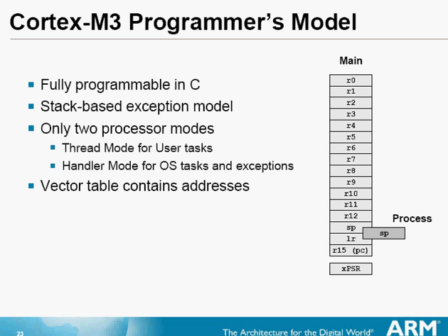Stack based means the PC, meaning program counter, PSR, LR, and corruptible registers are automatically pushed onto the stack upon exceptions in hardware, as opposed to manually doing it in software for other ARM processors. The vector table contains addresses that are fetched upon accepting an interrupt, as opposed to instructions.